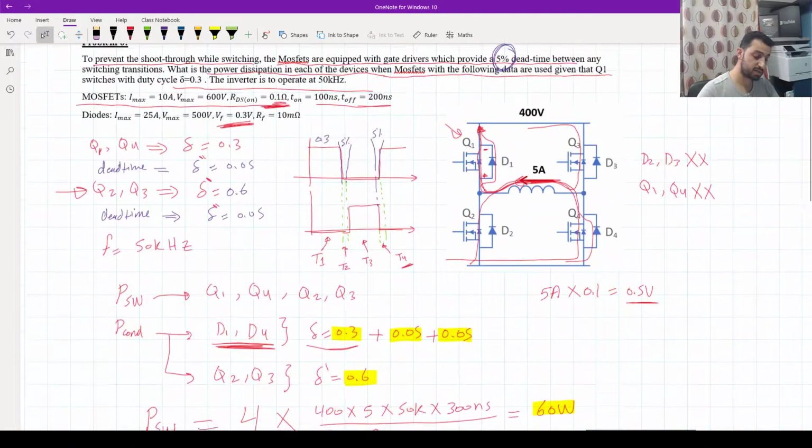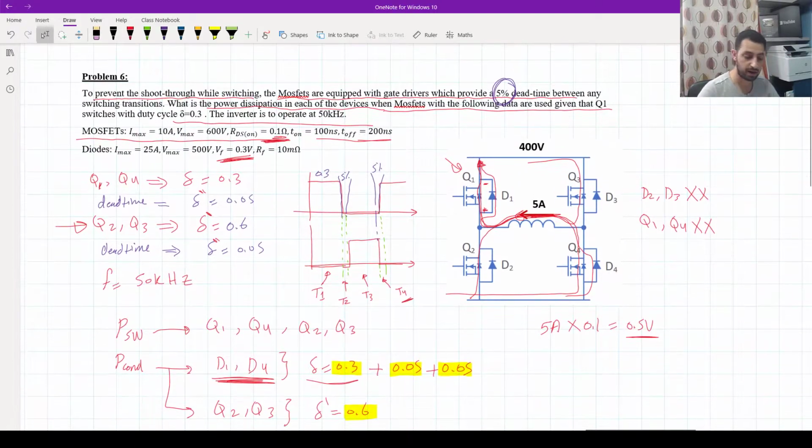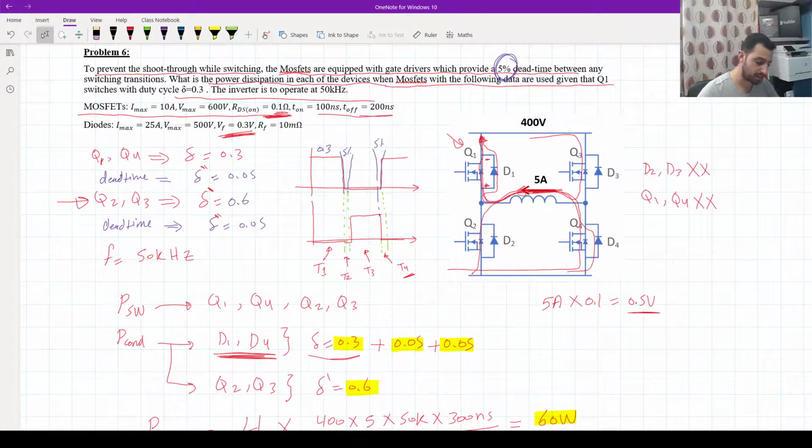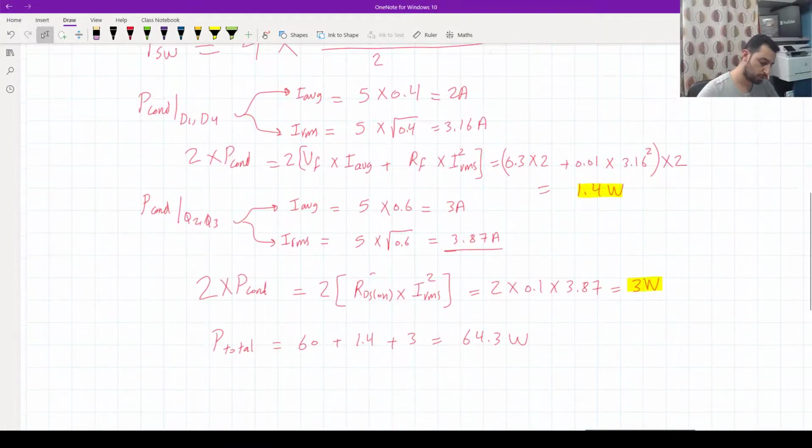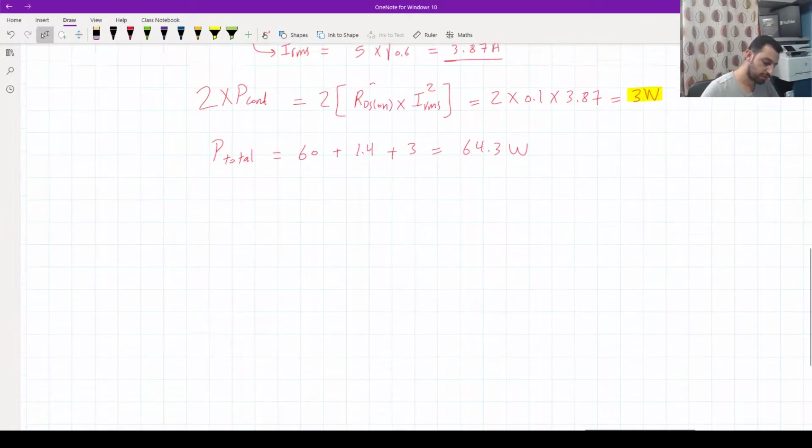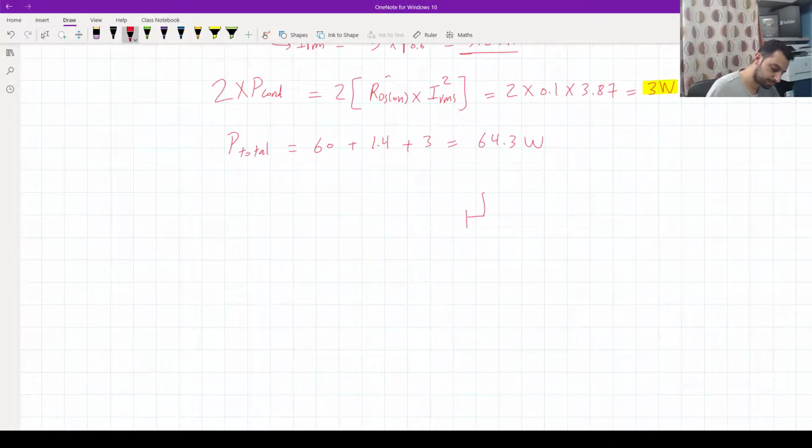And yeah, there are some assumptions in this question, and we assumed, for example, that once we turn on the parallel diode, all the current will go through that diode, but practically it might share it. And I will show you now just an example as addition. You don't need to calculate that. So if I have here a MOSFET, and that MOSFET has already a diode parallel to that, okay, as external one. So it's not the internal diode, it's the external one.